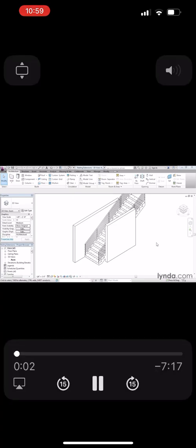In this movie, we're going to look at the railing extensions feature. We can take our railing objects and build in top rails and handrails, and these top rails and handrails can have automatically generated extensions. Those extensions will allow us to build in code requirements such as the distance of an extension required by the building code, or adding a tread depth and so on to the extensions of our railings, and have it take place automatically when we draw them.